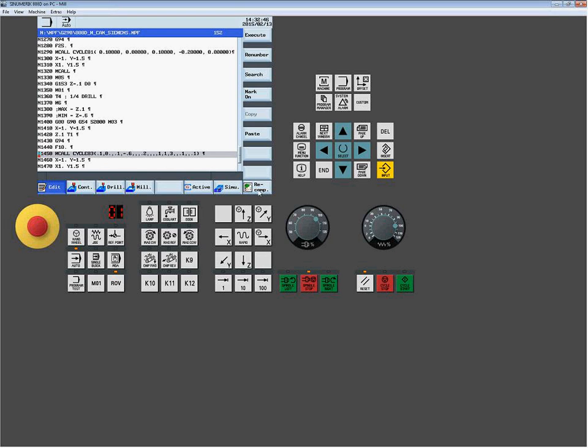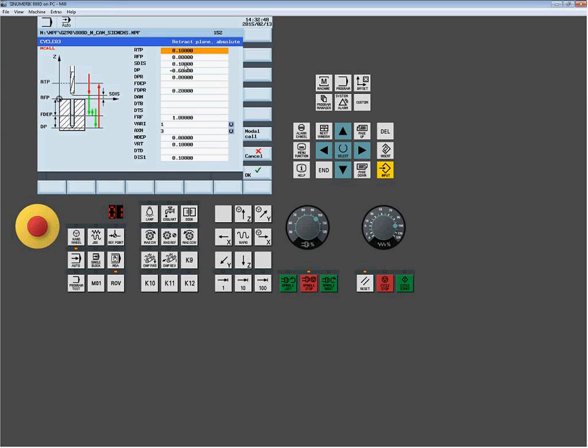And then what you do is you're going to open the CAN cycle, and the first thing you want to look at is the blank spaces here. Some are okay, but that usually tends to throw a red flag that you want to pay close attention, because they probably are not filling out all the variables. So then I would just simply go through the resulting cycle and validate that it's all correct, that the depth was in the right field.